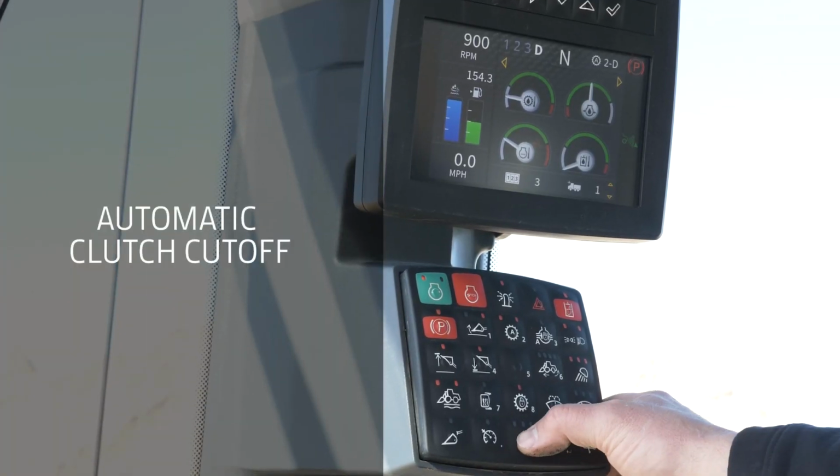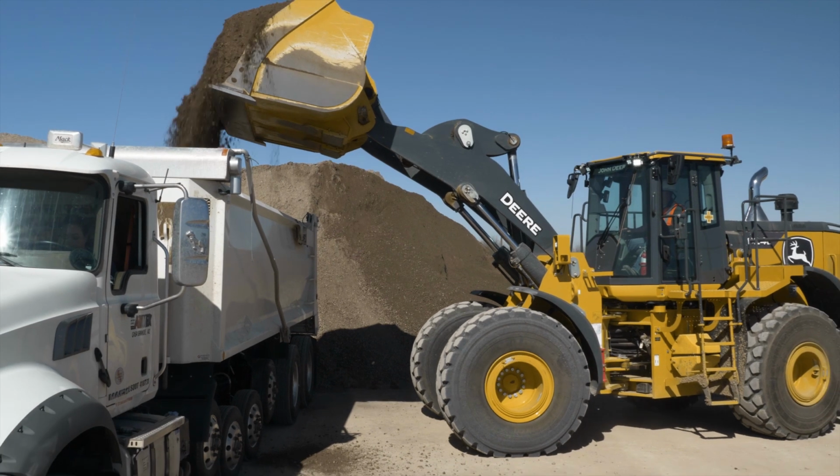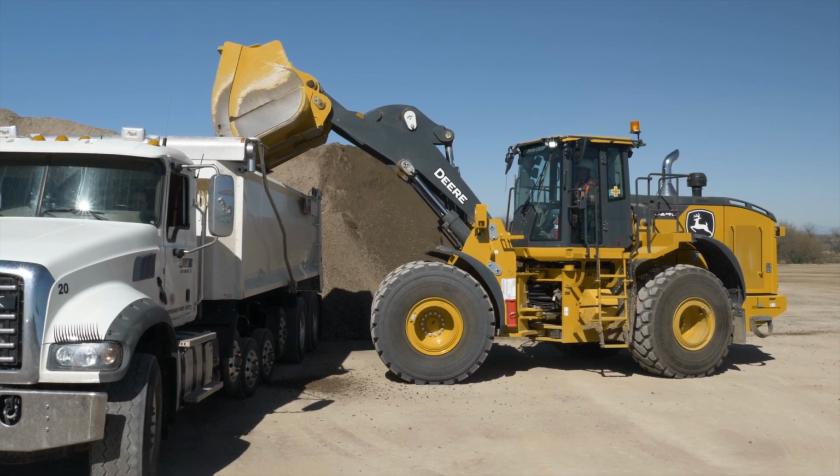Clutch cutoff neutralizes the transmission when the operator places the transmission in gear and the service brake is applied, allowing the engine's power to be used for the hydraulic pumps.